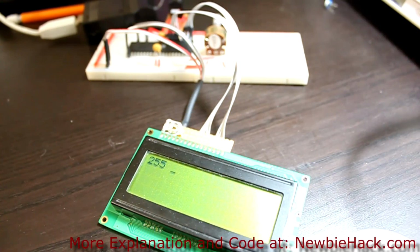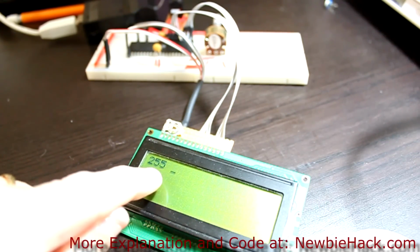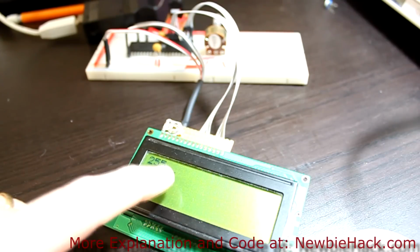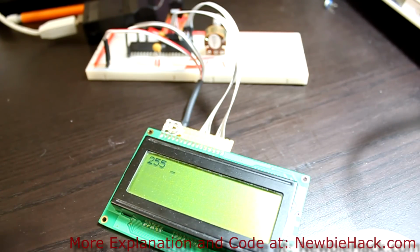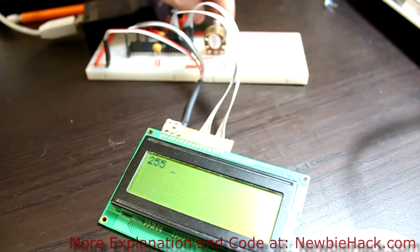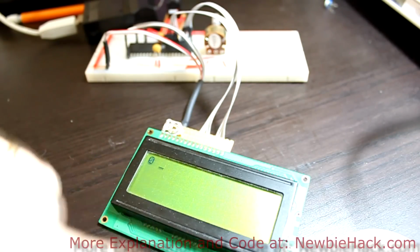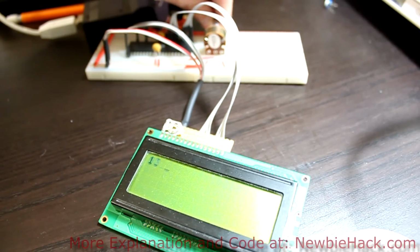Okay, we've reprogrammed with that space added. You'll notice that there's a space and then there's a cursor at the end. If that is annoying to you, you can just turn the cursor off using the special send a command that we talked about in the LCD videos. Let's see what happens when we turn the potentiometer. It looks like it's working correctly. I stopped it, started it again, stopped it. There you go, all the way to 0. So we have only a 0 there, which is exactly what we want.